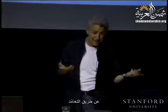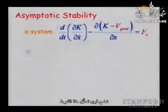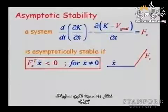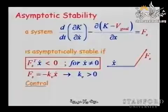So how do we stabilize it? Quickly: damping. How do we select our damping? To oppose X dot, we put forces that satisfy this condition. It's very simple. You just select F to be minus kV X dot with kV positive.